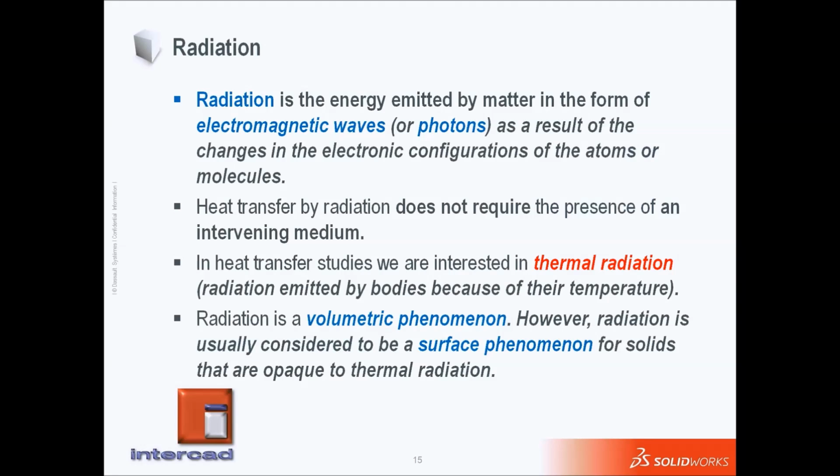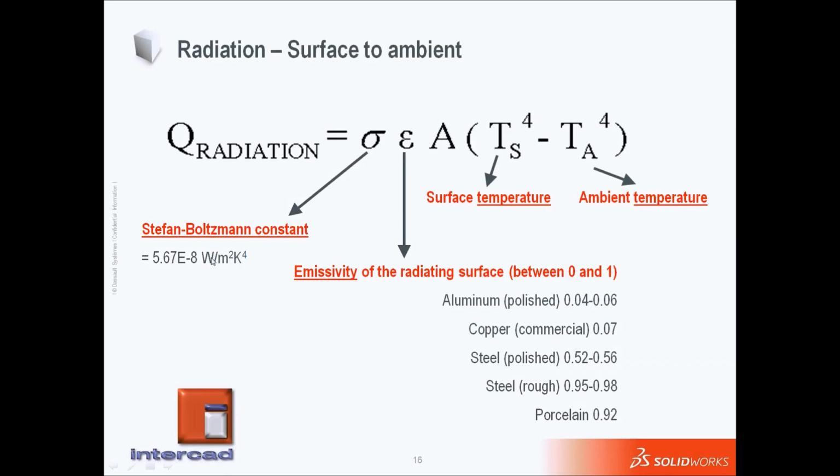Simply, radiation is the energy emitted by matter in the form of electromagnetic waves, and this is a result of changes in the electronic configuration of atoms or molecules. For this mechanism, we do not require the presence of an intervening medium, and although it is a volumetric phenomenon, we mostly consider it as a surface phenomenon where a solid is opaque to thermal radiation. For this type of heat transfer, we can formulate this as